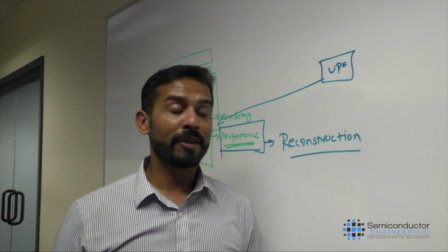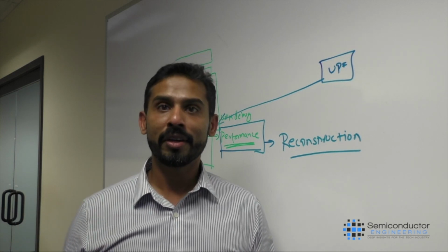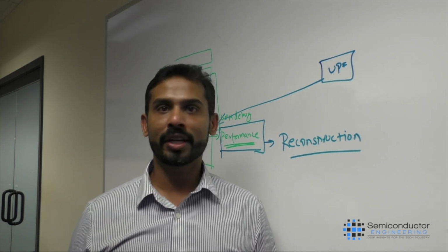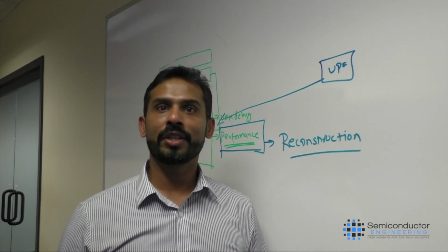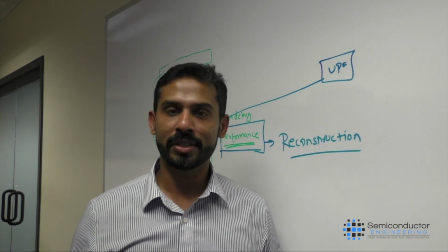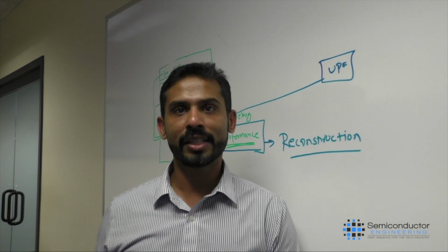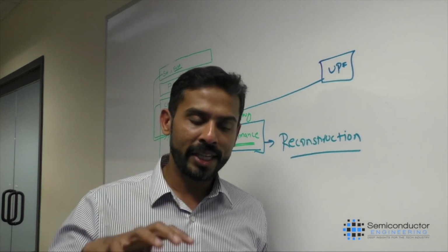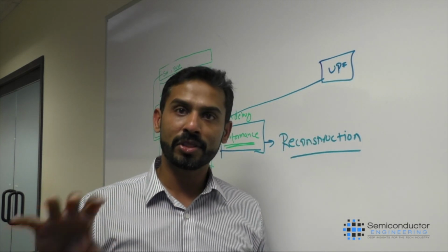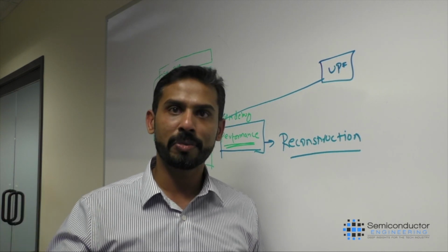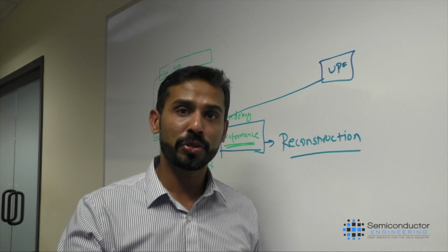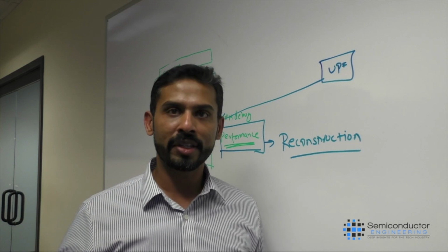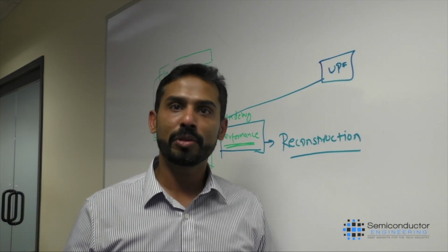So when verification engineers bring up their debug, now they've debugged their functionality, you turn on UPF. What happens, right? You don't want to go to a different context. What you need is a place where, whether it's schematic, waveform, where most of our engineers spend time, or your source code, you should be able to turn on power intent and say, okay, what happened to my isolator cells?